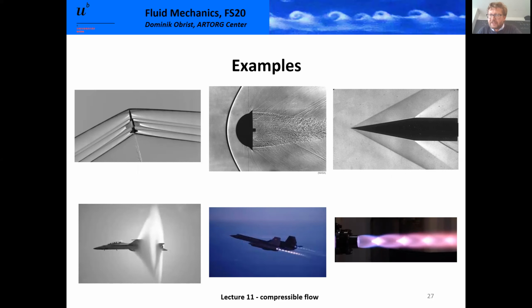I just want to show you compressible flows in the experiment up here. These are probably Schlieren visualizations, showing density changes in the flow, showing here a nice detached bow shock, or here very classical oblique shocks coming off a supersonic airplane, or here a pointed, probably a missile or something like that. And down here in practice, complex shock cells, diamonds they're called because they have this diamond shape, which are very classical. They come out of jet engines at supersonic speed. So it's a combination of shocks that are being reflected in a jet.